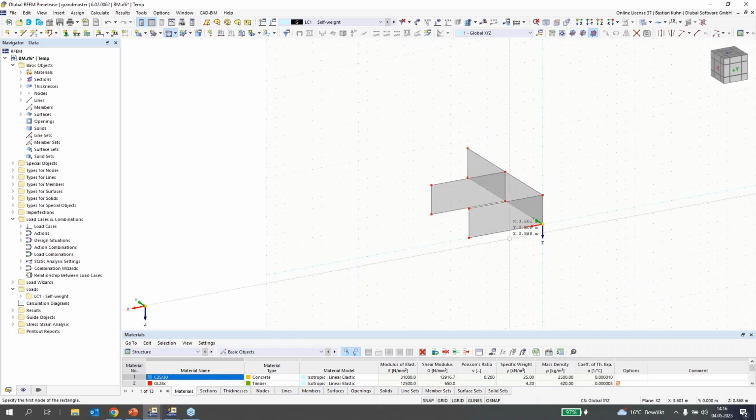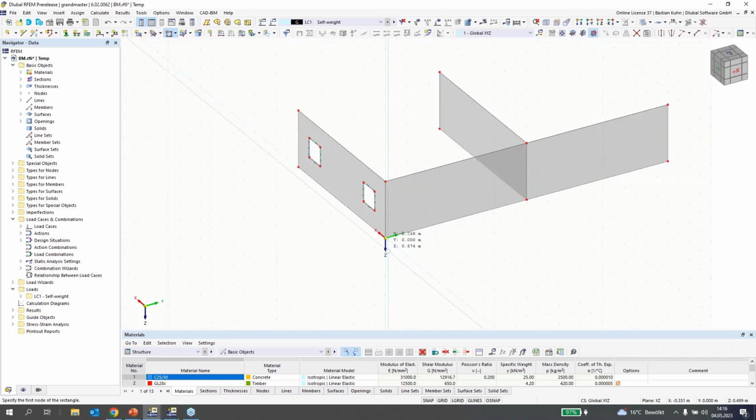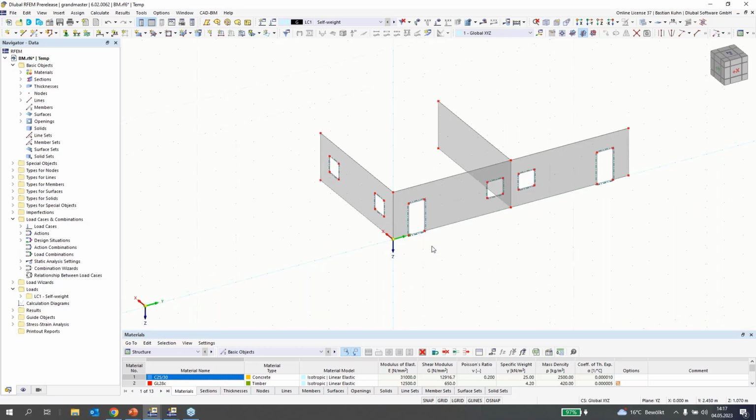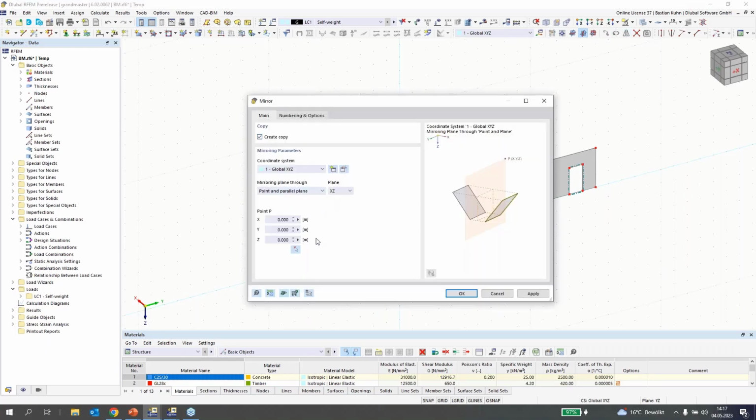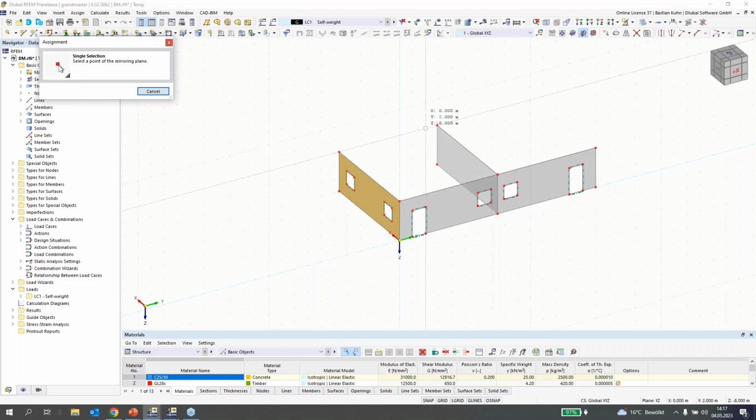Just, yeah, very simple openings in here, there. We'll do also the same, or not the same, but we will also put openings in here. So therefore we should get the other working direction. So this, and this, and here also something here and there. Perfect. And then we can copy this one. Oh no, not copy. We should mirror this on XZ plane by this distance.